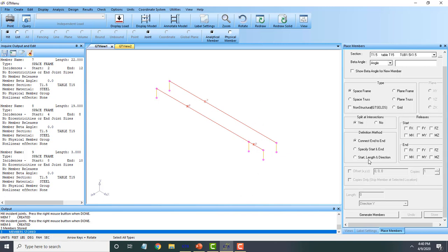Now I'm on page 73 of the PDF document, and this should be step number 41. Okay, so we're going to provide the inputs as shown in that dialog box in the document. 0.0625 is the offset distance. Okay, sorry, I have a negative here. It should be 0.0625 feet, and that's along the Z direction. So we're actually going to provide an offset there. The length of that member is going to be 22 feet. We know that, and we're just going to create 2 copies of it, right?